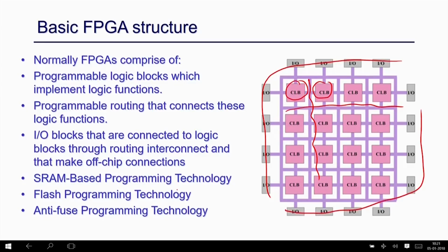This configurable logic block is, as the name says, configurable, so you can map your design here. It consists of both storage as well as logic units. Your design has to be mapped here, and the interconnection has to be done through the interconnection units. All these logic blocks are programmable, and the interconnection is also programmable, so you can make a connection from anywhere to anywhere.